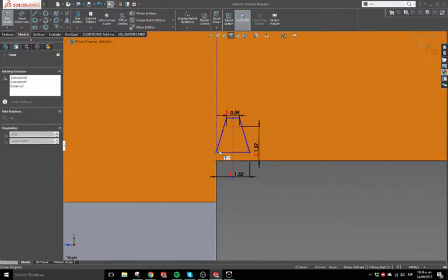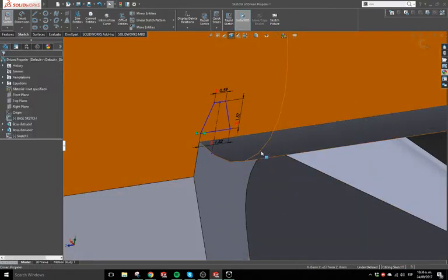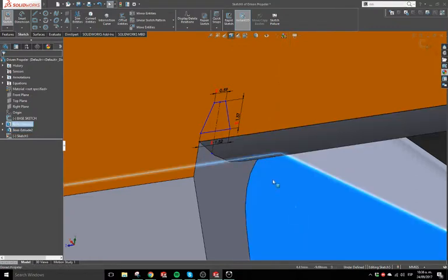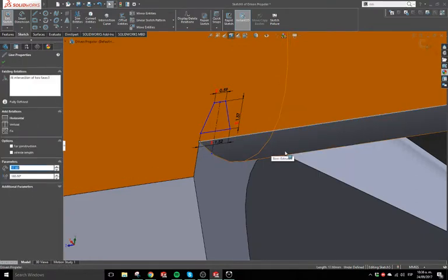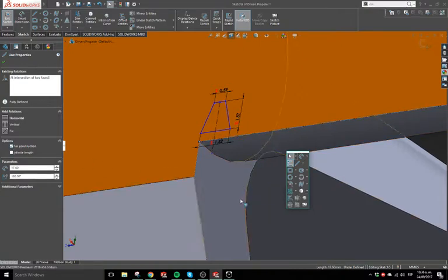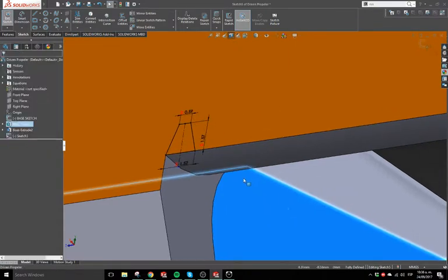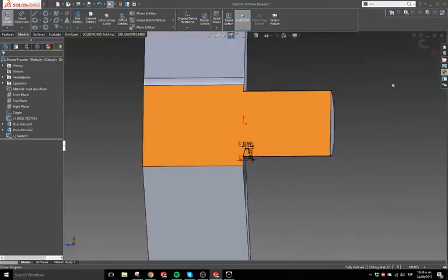Okay. Now, I have a technique you guys should know. Many people don't know that you can actually create intersection curves, which is pretty much where a body surface intersects a plane. It draws a line, so you can use that to snap for your sketches, which is really useful. So we make this for construction, and then we snap this thing here.